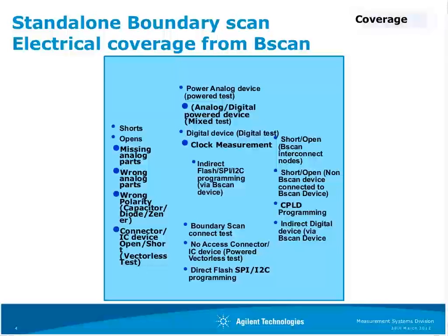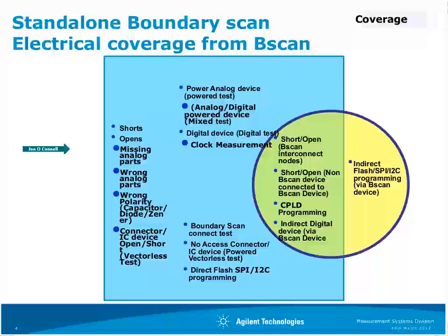But boundary scan is, whilst an excellent technique used for power test and for complex products, it also only has a specific defect spectrum, and it's normally its own standalone PC driven. So we're leaving all these areas, shorts, opens, missing, wrong parts, to be detected by other equipment.